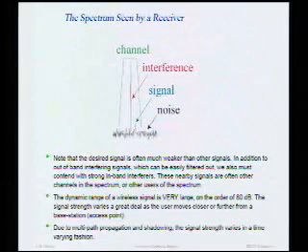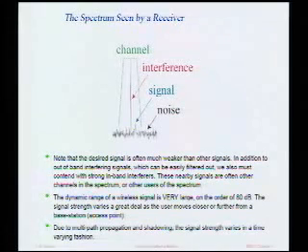Okay. The other issue that Al brought up was the dynamic range of the signals that we're receiving. You don't stand still and communicate, although there are point-to-point communication systems. Even in those situations, the signal strength varies. You might have to design a receiver that has to work over a few meters range to a few kilometers range. And that might mean a huge dynamic range in the signal that you're receiving. And I put a number here, about 80 dB, let's say, for a cellular communication system. This signal varies not just because you move back and forth closer and further away from your transmitter/receiver, but also because the environment over which you communicate changes.